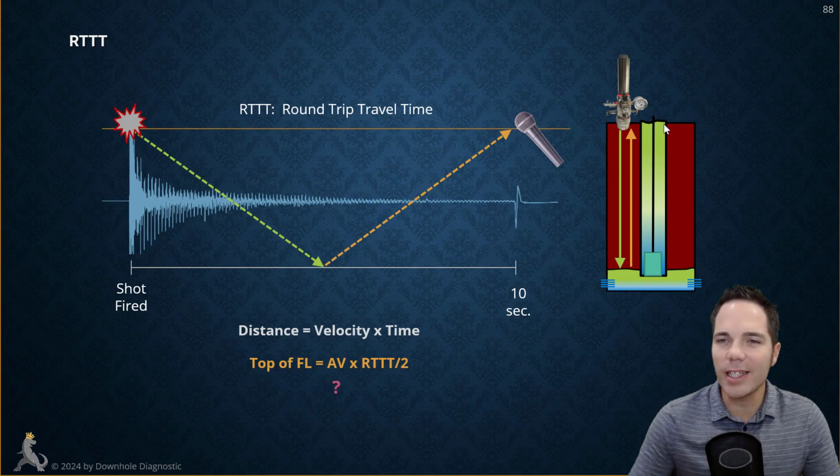There are various different things that can cause the acoustic velocity to move at a different speed, and primarily it's the composition of the gas. So do you have methane, ethane, propane, CO2, H2S? What is the composition of the gas? That's going to affect how fast that pressure medium transmits. Also, what is the temperature and pressure on average of that gas? That's going to affect the acoustic velocity, but we will look at that later in this section.